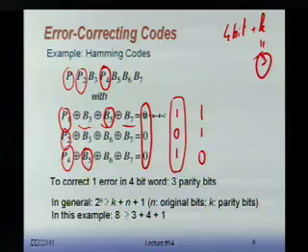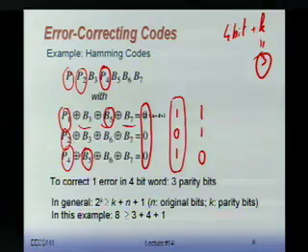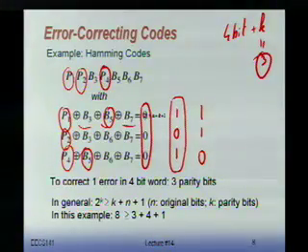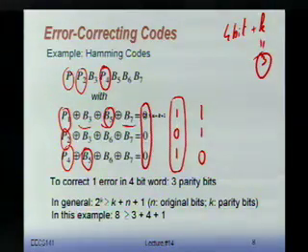Okay? Now, when an error happens, you feed it out. You always go to the decoder, right? All zeros, we don't have to do anything. If, however, I detect there's at least one 1 in there, we have an error. And we know how to detect it, because if there's only one single error, we can use that code to say, hey, flip bit 3 or flip bit 5, and your word is going to be correct again. Okay? So that's the way it works.